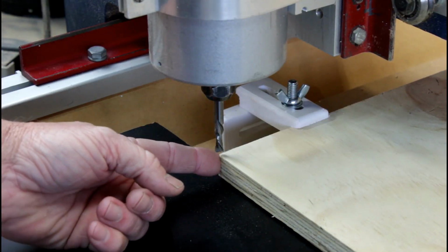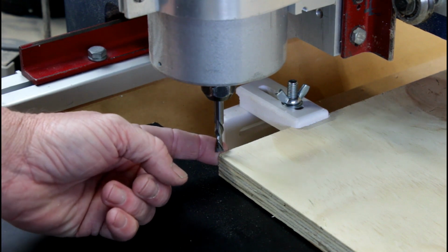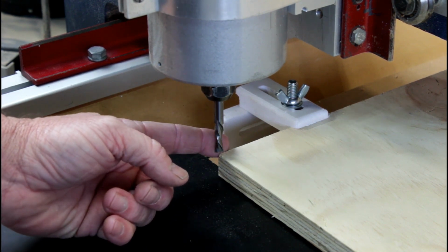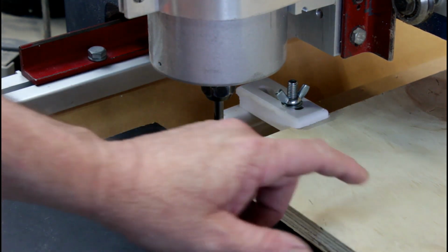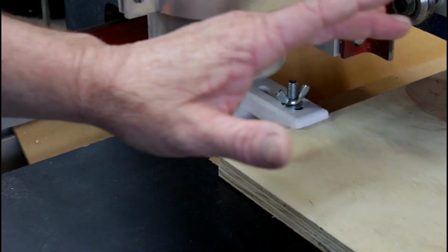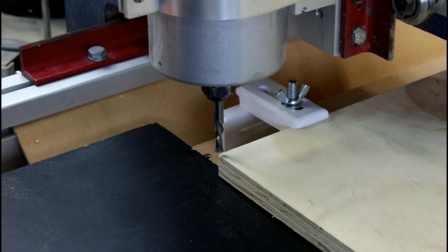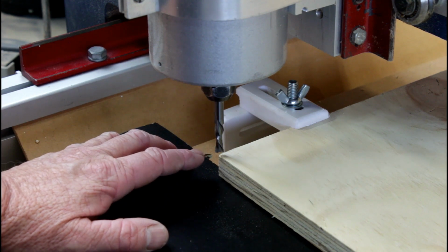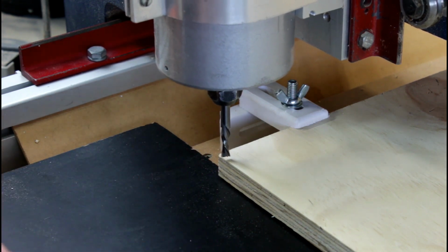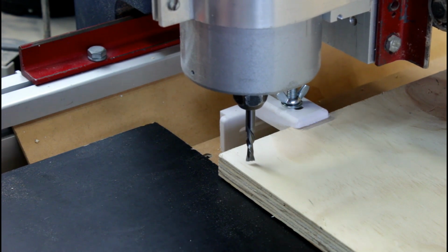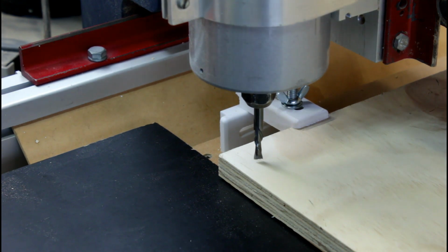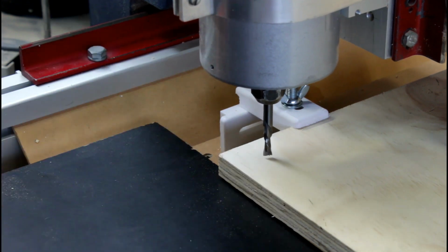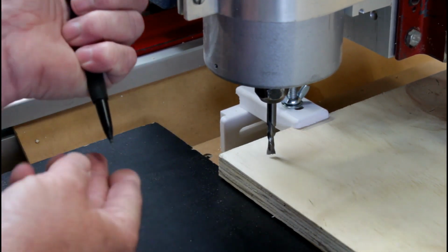I've brought my cutter here to the corner and set my X and Y 0. I haven't altered any Z setting that I did previously. So the cutter is still zeroed or set with respect to the spoilboard. And I'm going to be using this as a reference. So what I'm going to do now is take the cutter to some arbitrary position, say just here, and with a pencil I'm just going to put an X on the board.